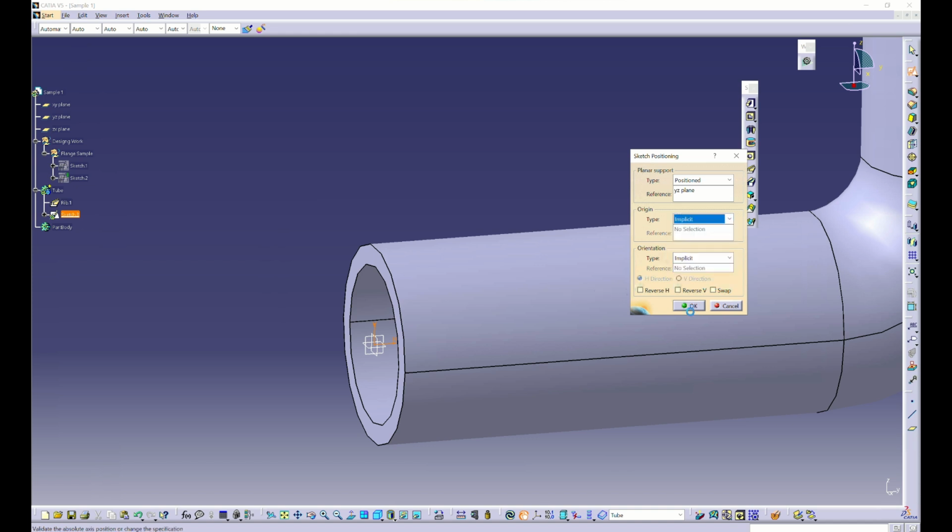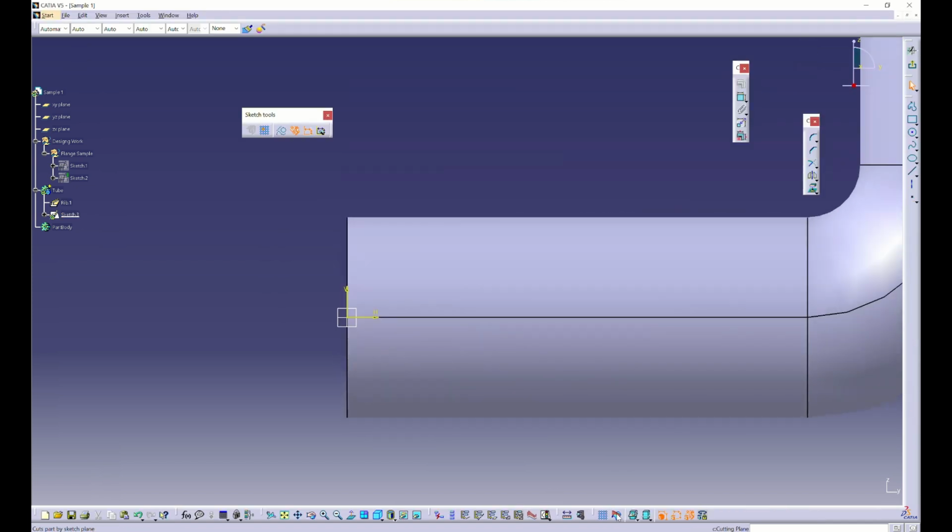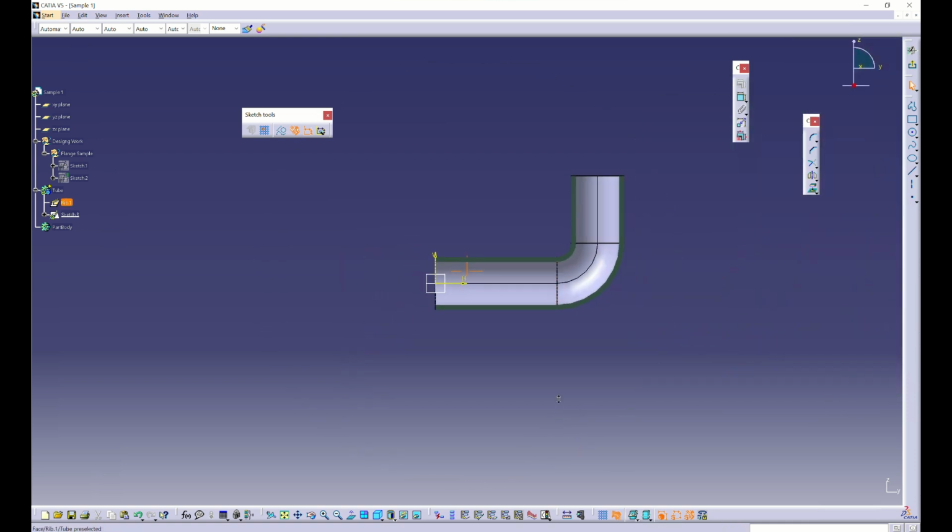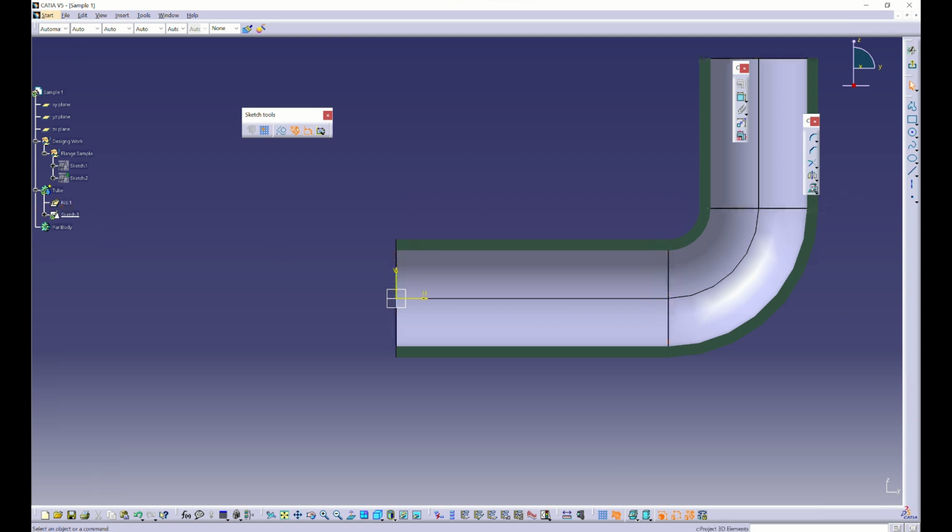I guess it's okay. Then using this one, we can cut. Using this icon, cut part by sketch plane, we can see what is inside now, so we can cut it physically. Then extract here using this projection view, projected elements. We can extract this. It's up to you if you want to isolate using this, create datum, or just make it live. So I'll just leave it as live.